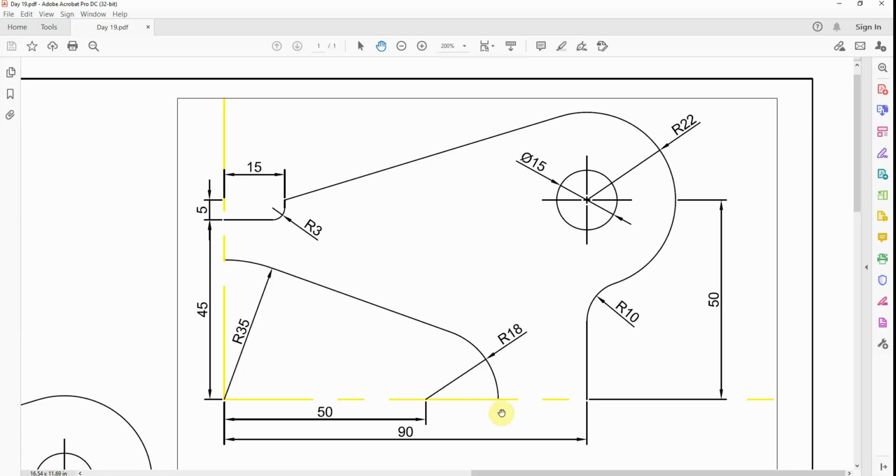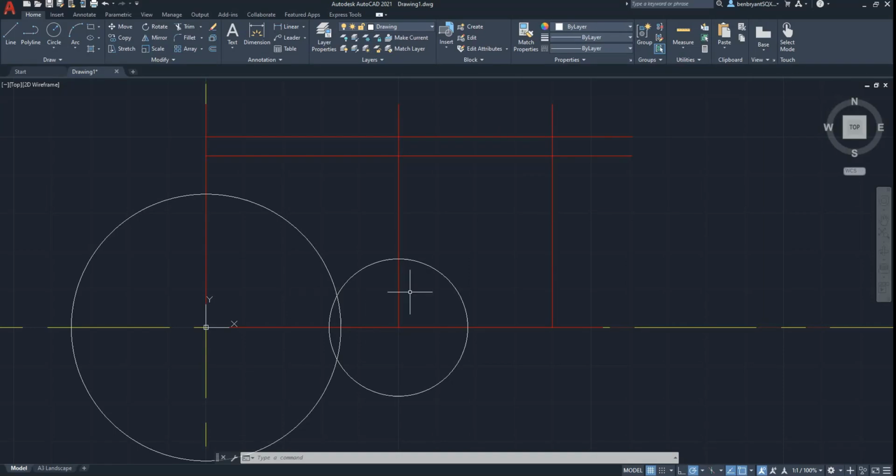Now if we look at the drawing, we only really have this corner curve into a tangent, into another tangent back into the corner. How we're going to do this is where it gets a bit difficult, because you can't pick up two tangents unless you define a location. So what we're going to do is draw a quadrant onto this tangent. That's now latched on.